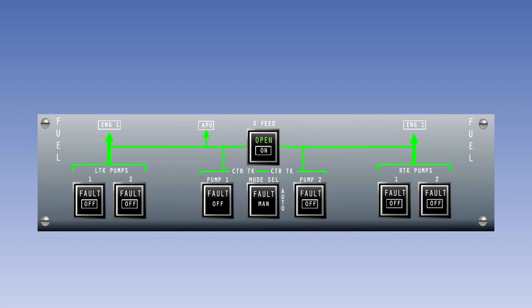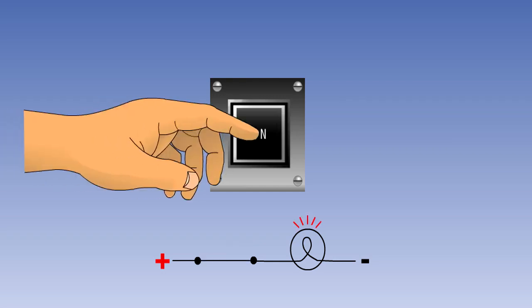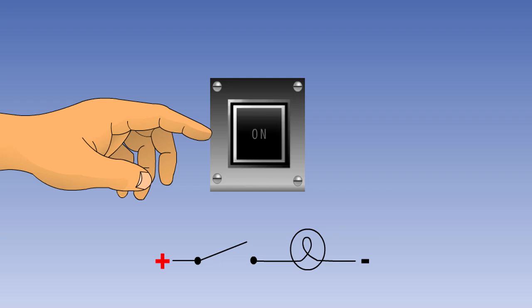Switch lights have largely replaced the other switch types in modern aircraft and combine the functions of a switch with the push action and an indicator light for the associated function. As with toggle switches, switch lights may be of the momentary action type, where the switch light is pressed and held to activate the service and released to deactivate it. Or they may be of the alternate action type, where the switch light is pressed once to activate a service and pressed again to deactivate it.